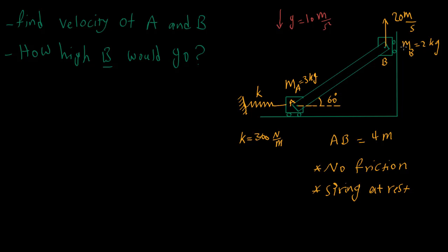And the same thing is true here. This slider is just moving upward and downward. So the reaction force of this surface is in the horizontal direction. Because it is normal to the direction of motion, it is always normal to the direction of motion. Its work is equal to 0.